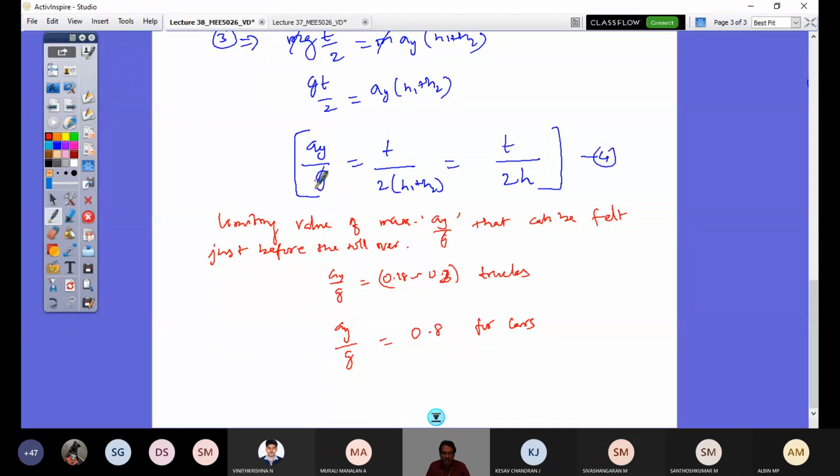It's an industrial practice that by looking at the dimensions of the vehicle, tread and CG location height, one can say what the limiting lateral acceleration during cornering is, in order to avoid rollover in the vehicle, right? That's very important. If the CG height is not elevated, that problem won't be there.